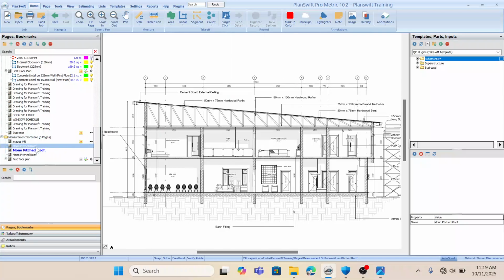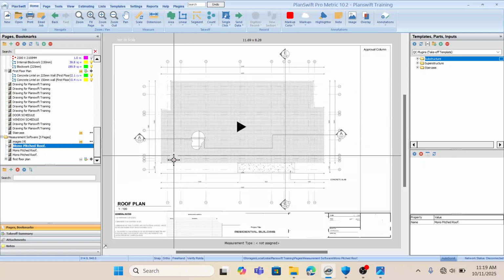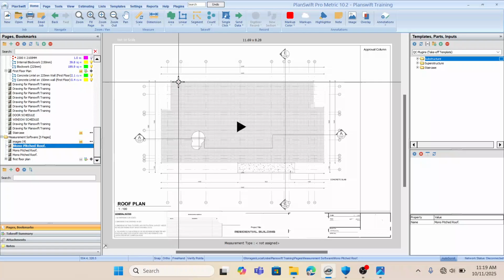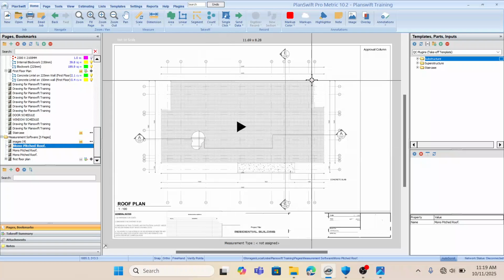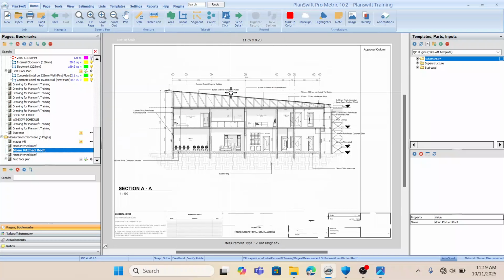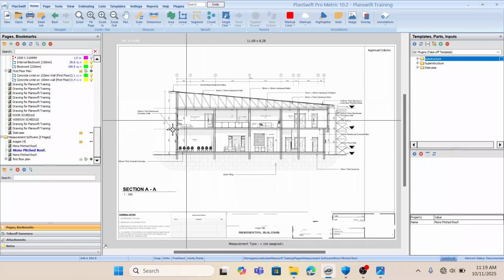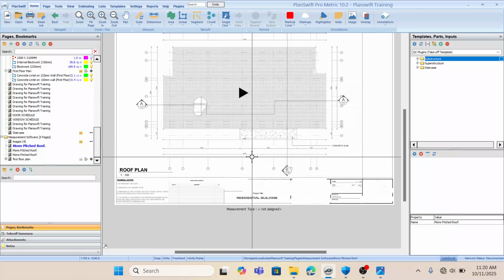They didn't state it. So that means since our distance is going to span this way, if you have a setup here, after 1,200, we'll have another setup. After 1,200, we'll have another setup, that way along the length of the building. This is a complete setup. Since they didn't specify, like I said the other time, let's assume 1,200. Let's calculate the number of setups we have. The length of this building is what? Let me check.